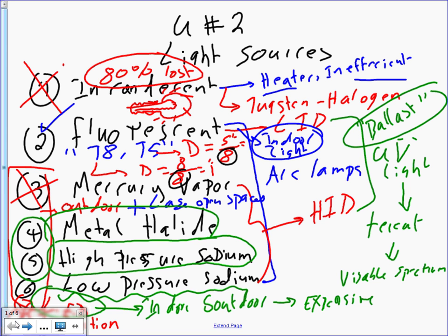On page 21, I'm going to look at the curve too. On page 21, they have the warm-up characteristic for high pressure sodium. It takes almost 6 minutes for high pressure sodium to come up to speed. Can you see that? The light output, the lumens, start, can you see the lower curve? The lumens start going up, up, up to their full value. The current starts going down, down, down to its value. Can you see that? The lumens go up as the current starts very high and goes down to its acceptable value. That's the inrush.